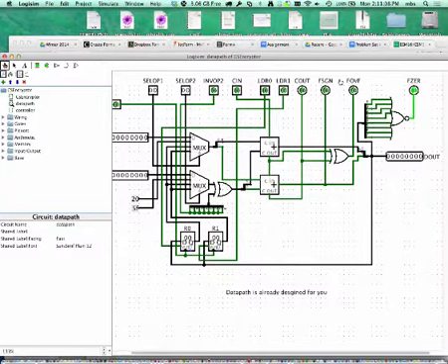So you can look at the MSB, that's the sign bit, flag sign, FSGN. You can check whether an overflow happened if you think of the number as an 8-bit 2's complement number. And you can also check the carryout. So you can do things like do some operation, and if the result is negative, then jump to a different state than otherwise. So you have all these bits coming up.